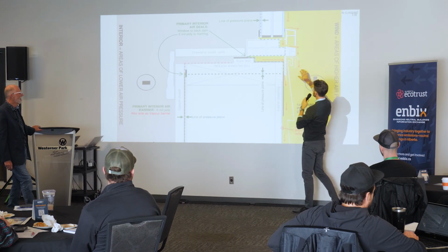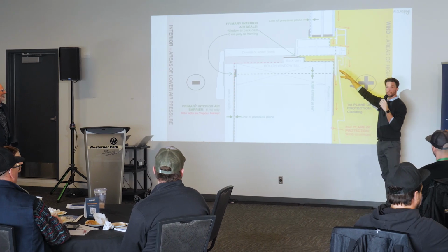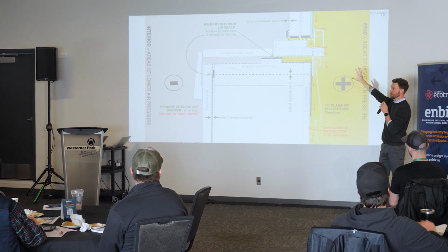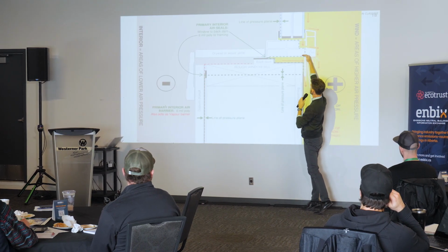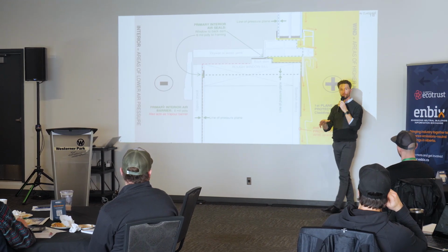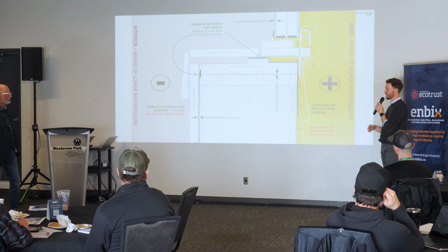And if you think about a slide like this, really, from this point up, all of those little red arrows, that's the domain of the window manufacturer to get that right. The window installer is worried about everything from this point down. That's what you have control over. And that's where we have to focus on understanding that sill and that back dam condition.